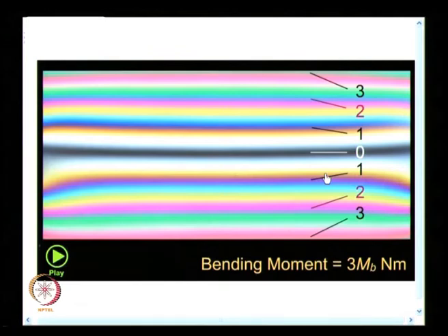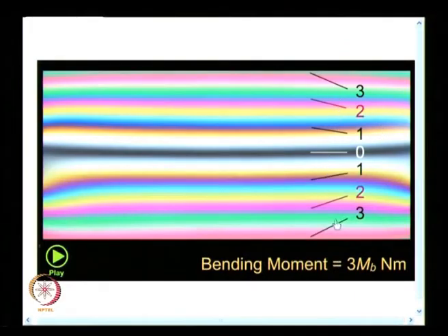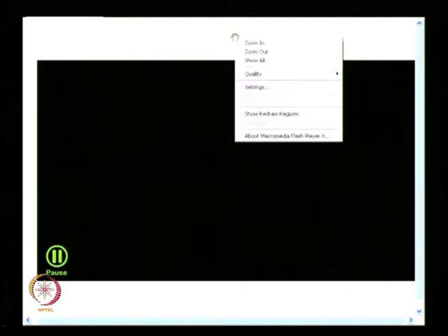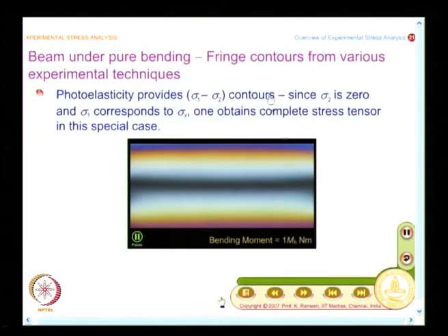And with developments in digital image processing, techniques like three-fringe photoelasticity have been developed, where you could pick out these RGB values very comfortably and then label these numbers. One of the challenging tasks in any optical technique is how to label these numbers. This is not trivial, and this is where many people want automated techniques, to minimize human intervention.